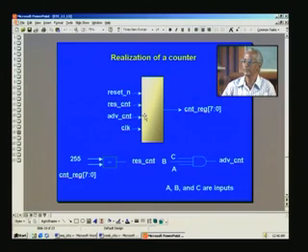And if you want to reset when the counter reaches say 255, in this case it may sound redundant because the next value will be automatically 0, it will wrap around being 8 bits, but any other number you want here you can also use, that is why it has been put in a general fashion like this, right. And there must be a clock and a reset also, because all flip flops normally need a reset, power on reset as such.